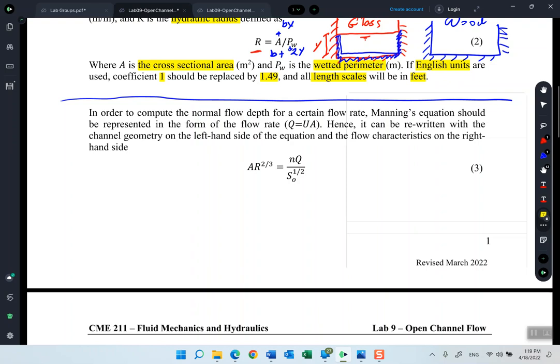It's a man-made rectangular cross-section that has the water flowing inside. So this is the practical use of open channels. The designer of this open channel used the Manning equation to be able to decide the elevation of the sidewalks and the elevation of the rail, so people do not fall inside. And if there is anything that increases the flow rate, this will cause flooding. So the designer will have to make a certain factor of safety.